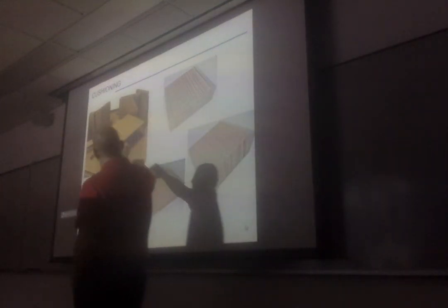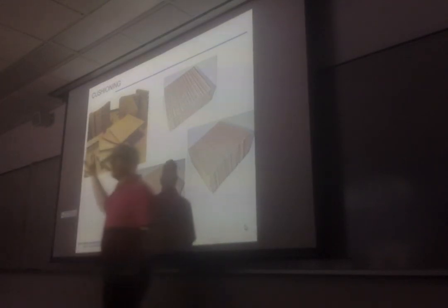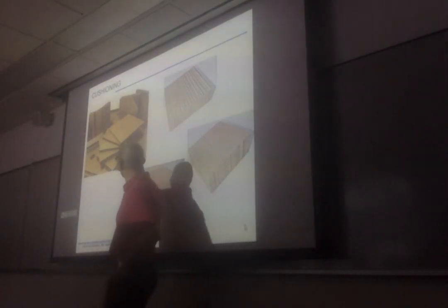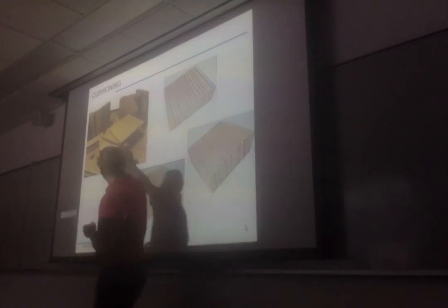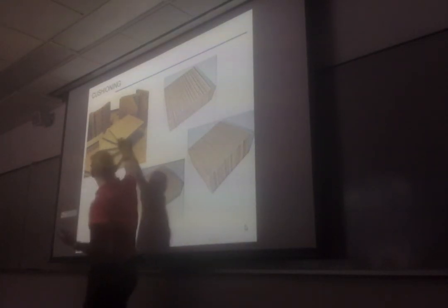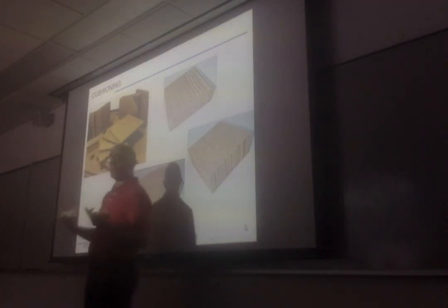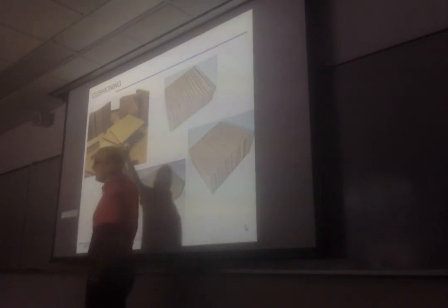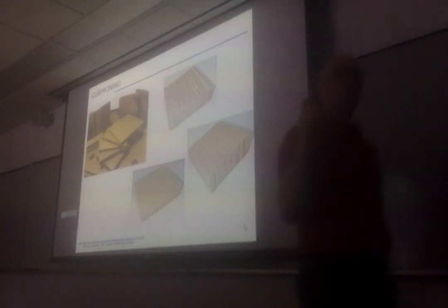One product that is used quite a lot is honeycomb. This is really stiff boards. So if you have a heavy product, if you want to maintain that in place, you can have a shape that will match your product, and you can have different levels of them. They are pretty good, particularly if you have a heavy product. If your product is light, it may not be able to deform in the direction of the honeycomb, but if you're shipping mechanical parts, like engines or motors, even in the axial direction of the honeycomb, then you can have pretty good protection.